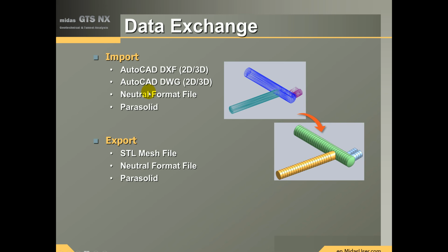For exchange, you can import geometry from commercial CAD software, as I previously mentioned. It has robust options, meaning that no data in terms of edges or surfaces are lost during the import operation. Once the geometry is imported, there are a variety of different tools to fix geometry shapes. For example, where you have gaps between edges that could not be connected, i.e. where the CAD draftsman missed it or separated the edges and hasn't connected them properly, NX can basically remove these gaps so you can create your surfaces and meshes and things like that. Geometry and mesh data in terms of nodes and element tables can also be imported and exported.